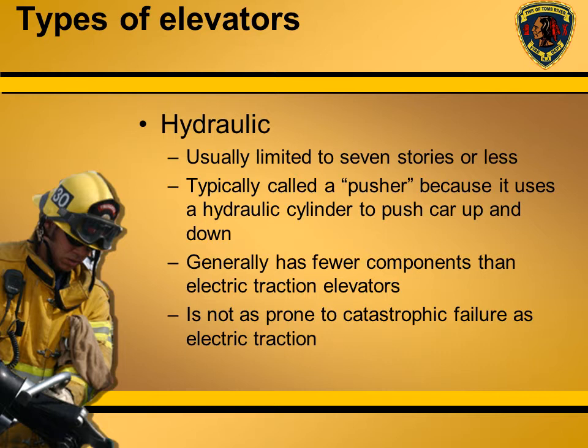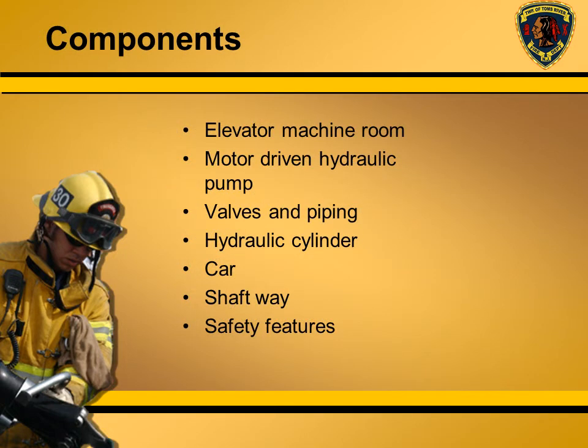Most buildings that are 7 stories or less utilize hydraulic elevators. Hydraulic elevators are less expensive than cable elevators, have fewer components, and are less likely to have a catastrophic failure. Both cable and hydraulic elevators utilize a machine room or a penthouse.